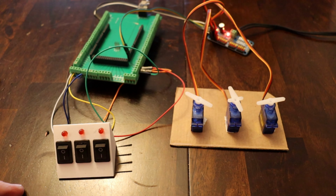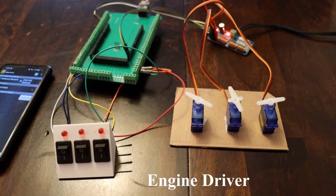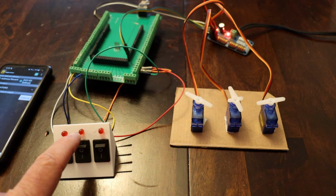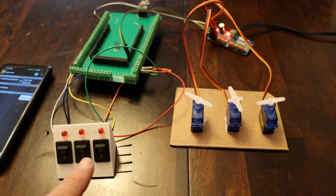turnout switches. And next we're going to go ahead and go on to using momentary switches. The benefit of doing it that route with the momentary switches is you'll be able to control them with your Y throttle. You'll be able to control them with pre-written scripts in your automation file. You can control them with JMRI, and in every case, it will indicate with the LEDs when it's in the thrown position, and you'll still be able to adjust it as you want. So we'll continue on with that next.